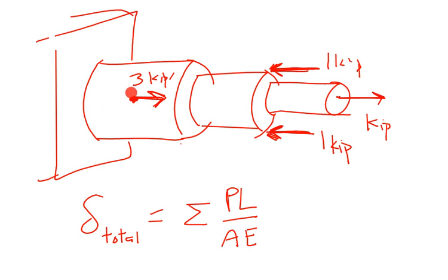Once I encounter an external force or an applied force, I know that that force will split this into two segments. Okay? So once I start here, once I get here to the force, I know that's one segment, and I keep moving. Once I get here, that's going to be a change in area and maybe a change in material, right? So that's a new segment. I now have two segments. I keep moving, nothing changes until here.